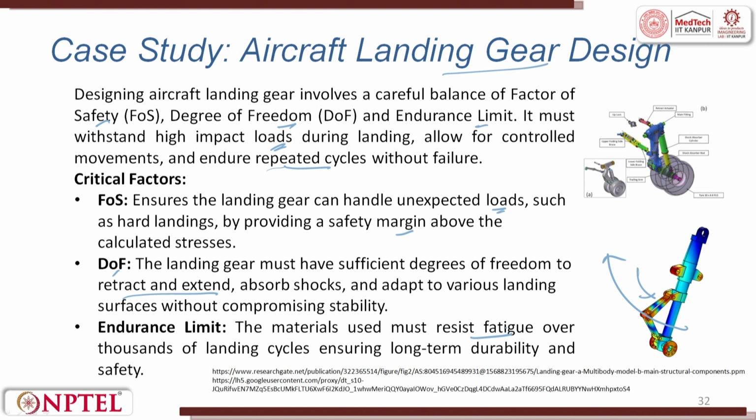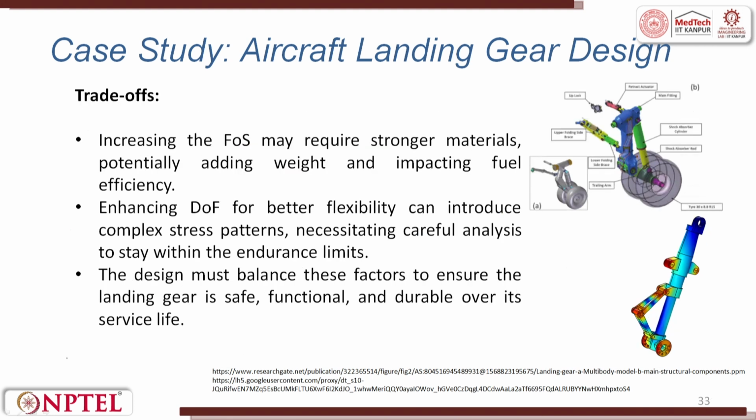and safety. You see how factor of safety, degrees of freedom and endurance limit are very important for a subsystem in a plane, that is landing gear. The trade-off: increasing FOS may require stronger materials, potentially adding weight and impacting fuel efficiency. Enhancing degrees of freedom for better flexibility can introduce complex stress patterns, necessitating careful analysis to stay within the endurance limit. The design must balance these factors to ensure the landing gear is safe, functional and durable over its service